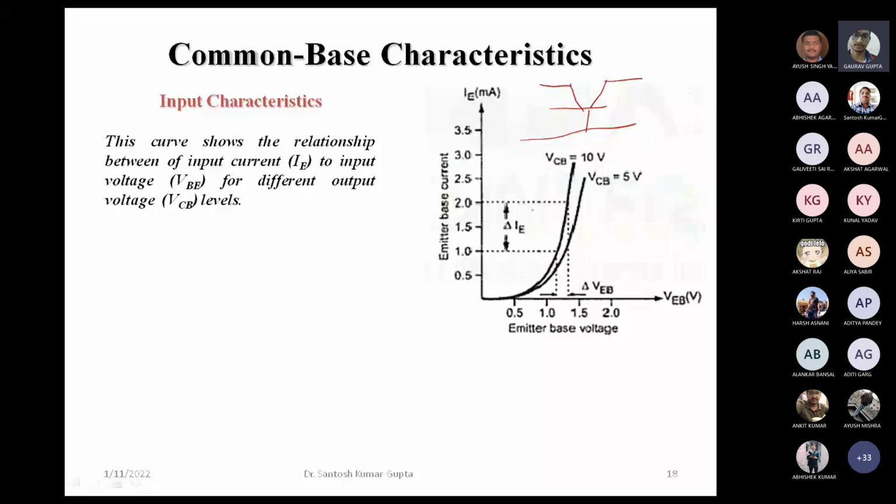So here, say we have any of these transistors. Say this is a PNP transistor. Then for the normal operation, we have seen that the base emitter junction has to be forward biased, and this collector base junction has to be reverse biased. There is no need to write it, but for illustration only, we are writing it here.